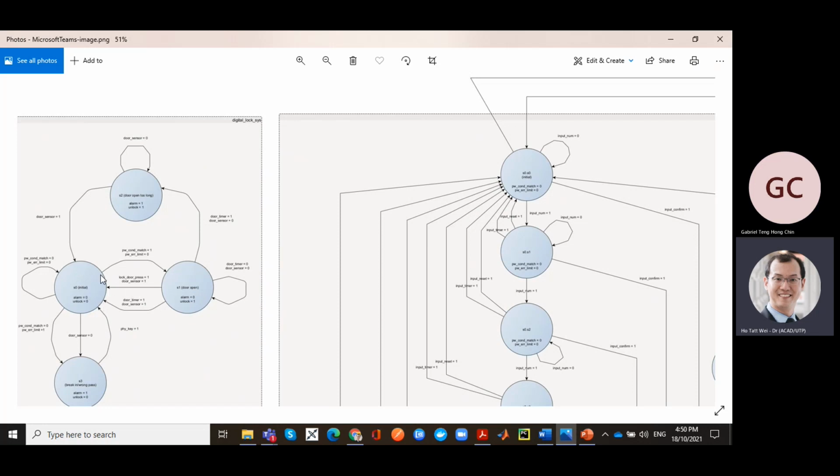So here the condition is met. Okay, so sensor equals 0. So you have a door sensor. Door sensor equals 1, you always go back. Okay, so that's fine. It's quite foolproof. So you can actually have maybe a door sensor; once the door sensor equals 0, you can just force it to stick into one state. No problem. But even if you leave it like these two, at this moment I can't see any catastrophic failure, so it will still pass. Okay, Gabriel?